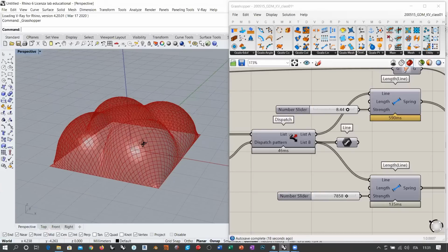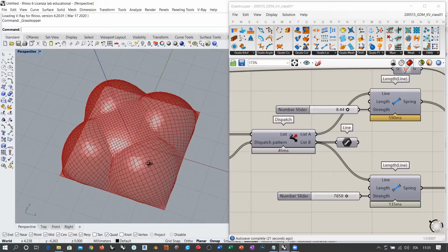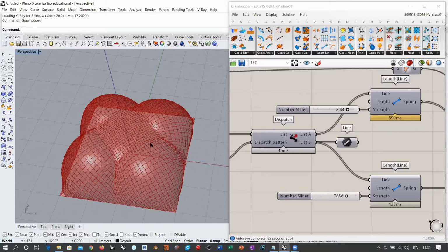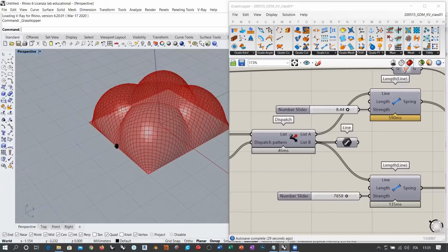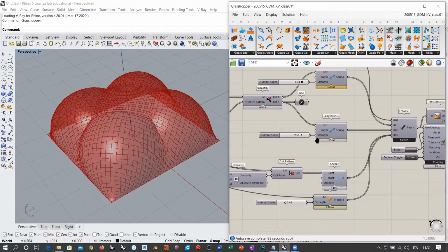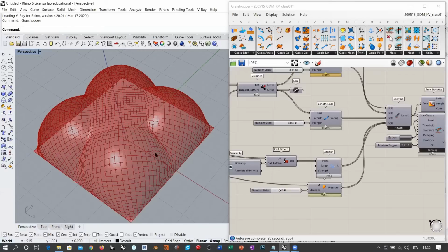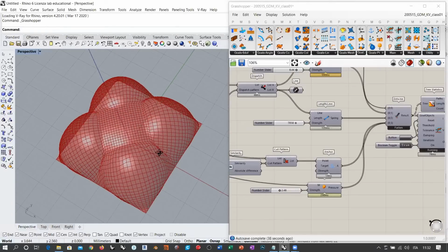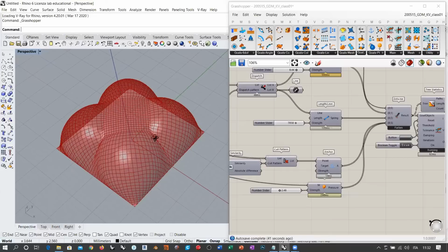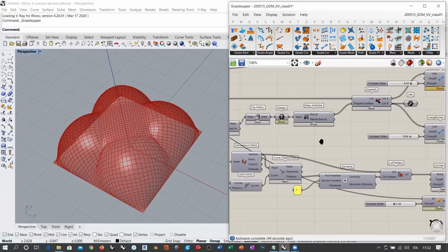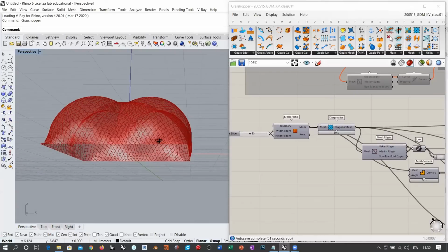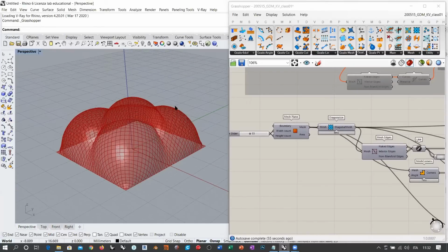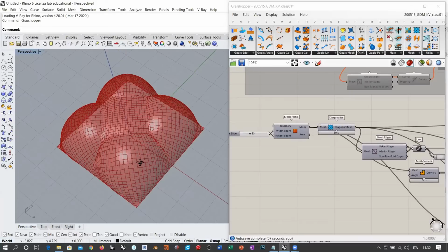And one last consideration is that this type of object, this type of shape is very nice, and it's very difficult to obtain it with direct modeling. So you can also use this method here, like inflatable structure, to create some nice geometry. But in that case, you must pay attention to few details. For example, even if you work with a high resolution mesh, like I'm doing right now, this has become a mesh with 1000 faces. So it's quite high resolution for a square panel. You always get this faceted aspect, okay, because you're working with a mesh.